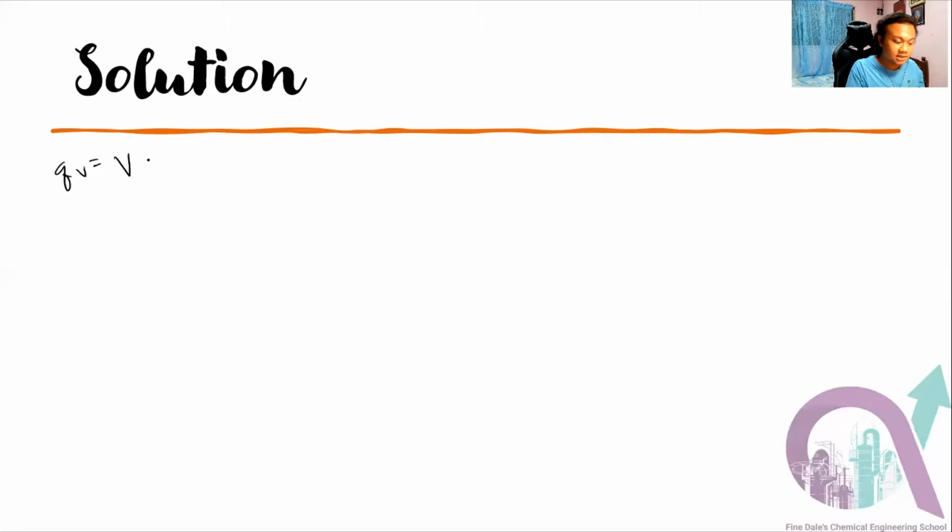We have this, HB equals HL plus V, CP of the vapor times the vapor temperature minus the feed. Okay, so that's how you do that. And then isolate V to the left side, and then you can get everything here.